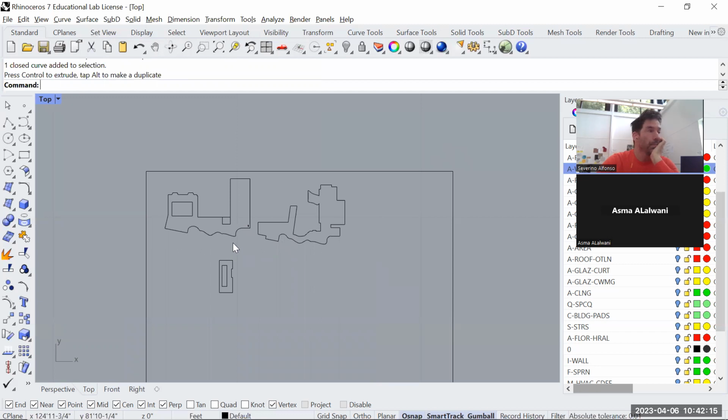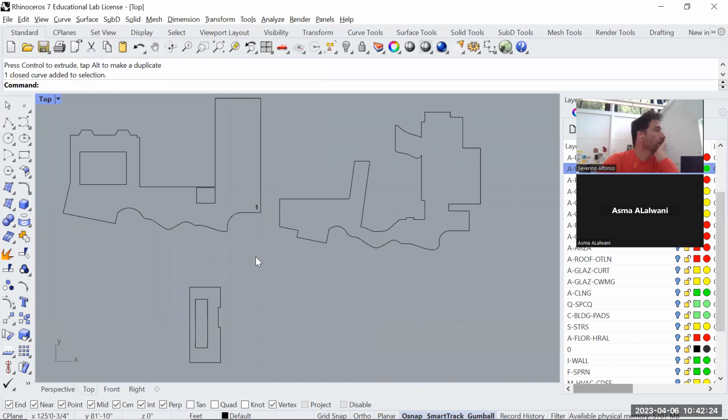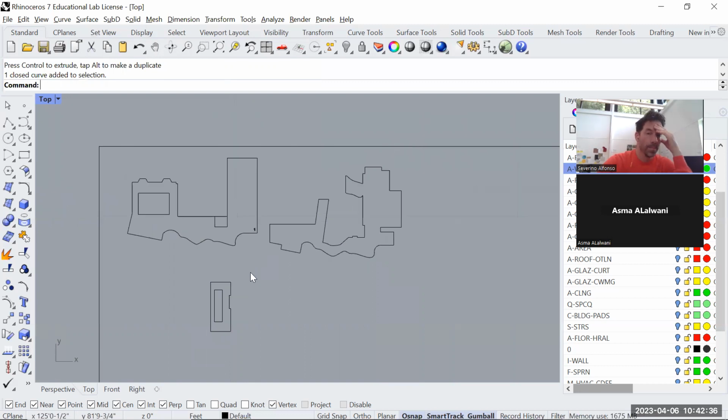Why do you have to bring in the AutoCAD scale drawing? No, you don't have to. We are just suggesting that because in AutoCAD, the model remains at the real, actual size, right? But in paper space, you can reduce the scale. If you have a 30-20 sheet, you can make a paper space of 30-20 and see what scale will be feasible. Maybe you want to go with 1/32 or 1/16, depending on that. It just gives you a better idea of the scale.